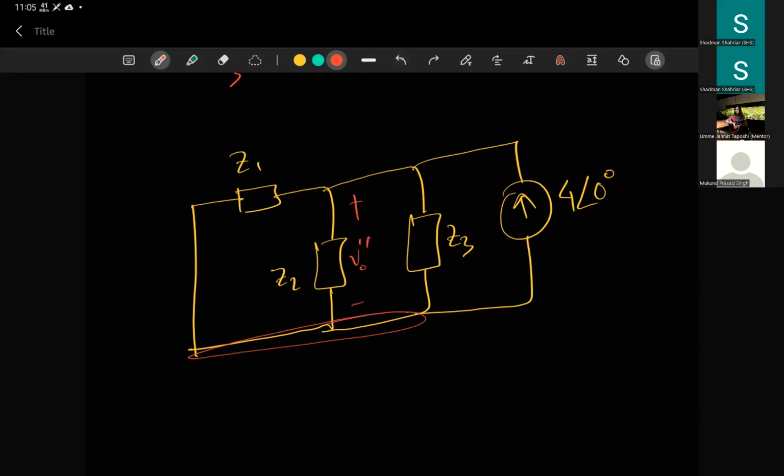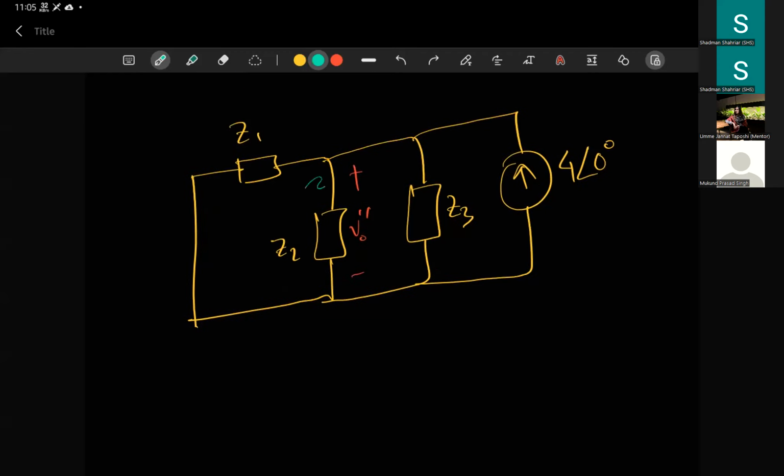There are only two nodes in this circuit. So if you are doing current divider rules, you have some current and you have multitudes of resistors or impedances, doesn't matter. And if you're trying to find some current, for example, if we are trying to find I2, I should mention there is a controversial equation, okay, kind of, there is controversy about math, but the thing is, usually students learn a special case, but please remember that that is only for two resistors. I'm going to show you the general form, okay?